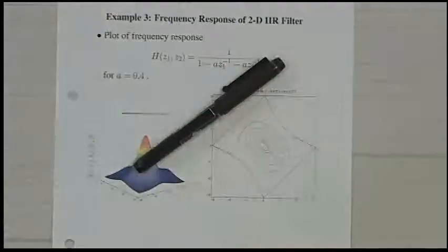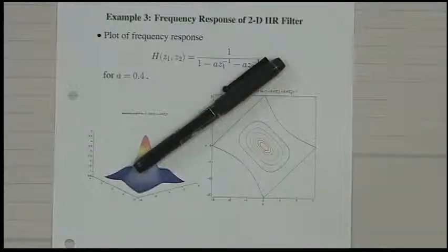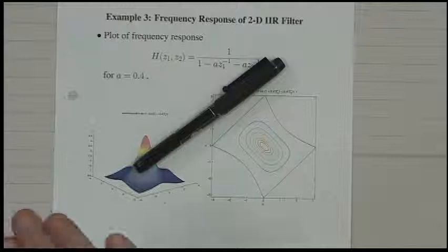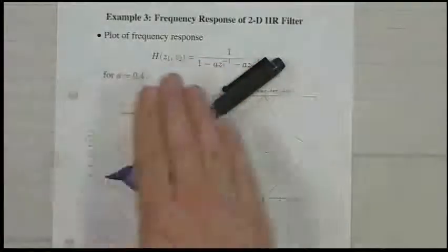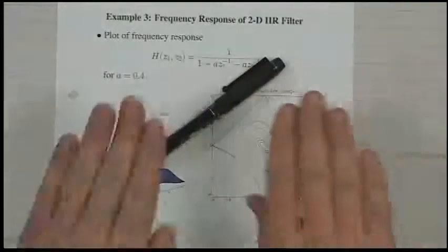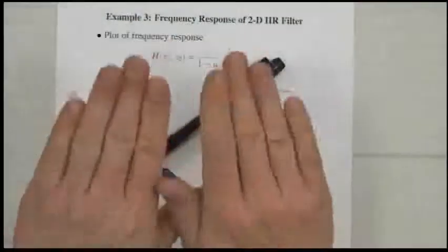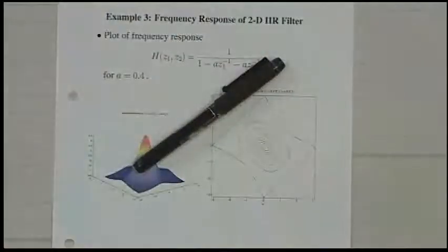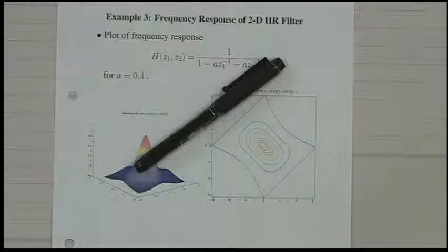So, for instance, is corrugated cardboard isotropic? No, because everybody knows corrugated cardboard has little folds in it along one direction, so it's easier to bend it that way than the other direction. So it's not an isotropic material. Any crystal is not an isotropic material because there are crystal grain boundaries that it will break across.